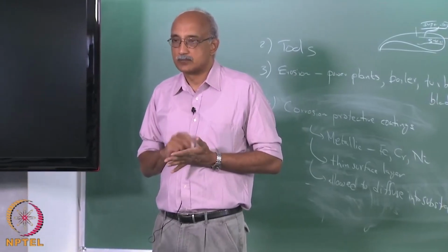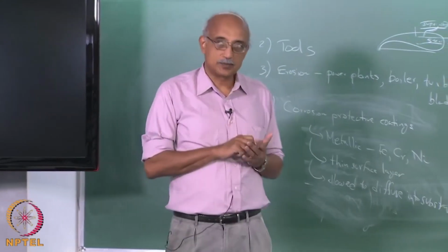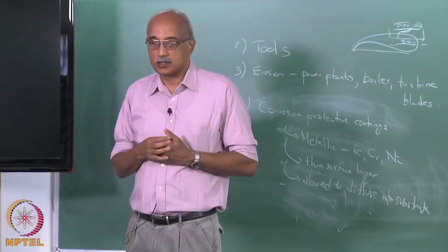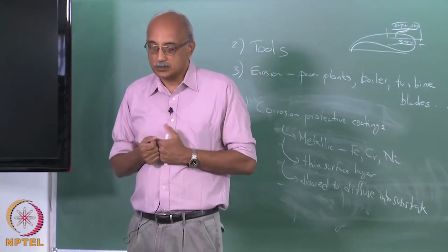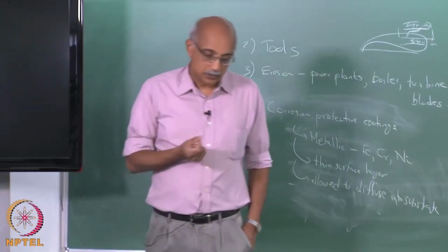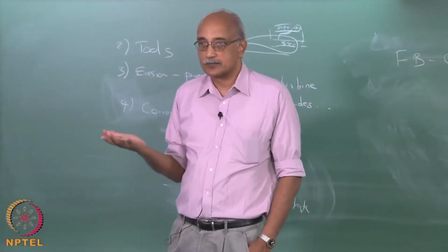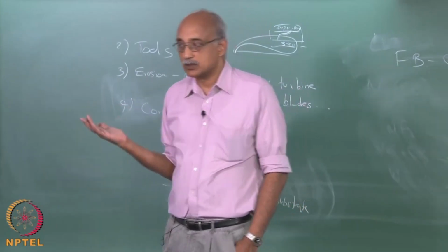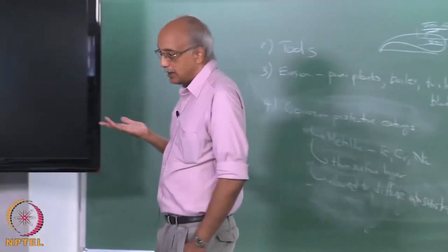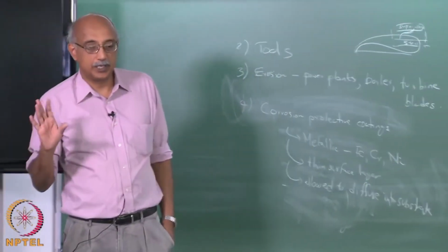Plasma enhanced CVD, because that can be done virtually at room temperature, and the plasma itself will have multiple uses. It will provide the energy to improve adhesion. Plasma can also energize the vapor phase molecules, plus it can actually, when you irradiate a low surface energy surface with plasma, you can increase its surface energy. So, you can take a polymer and increase its surface energy by exposing it to a plasma. You can almost make it behave like a metal in terms of surface energy characteristics.